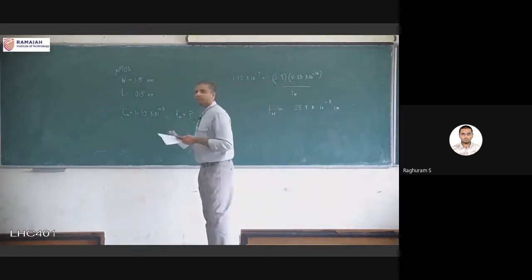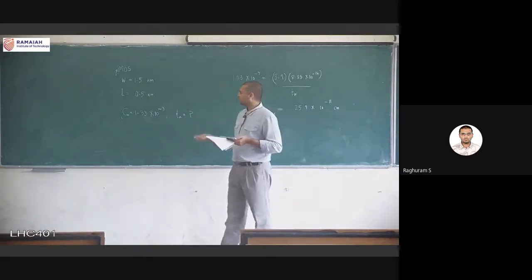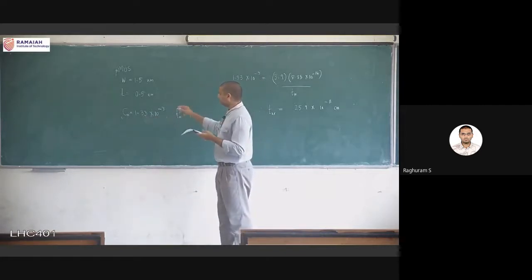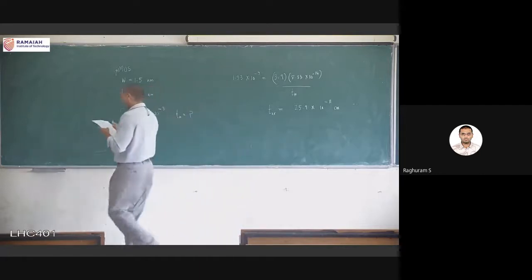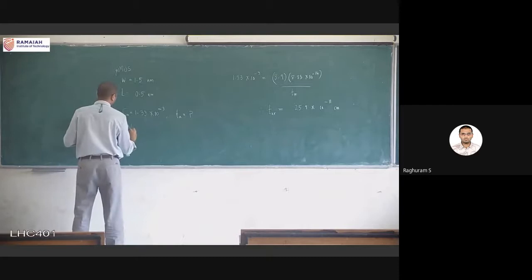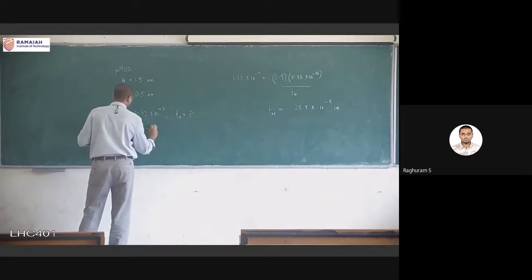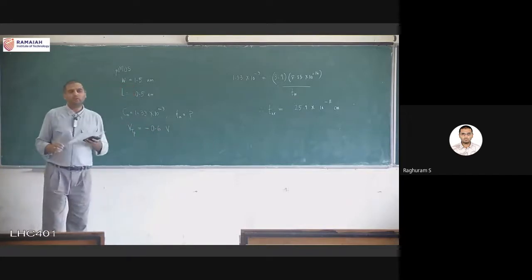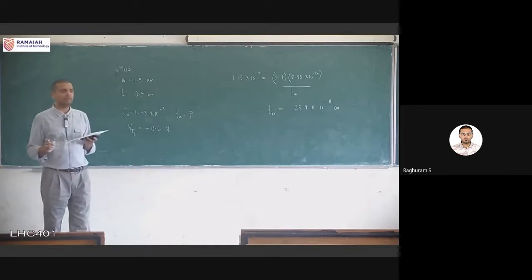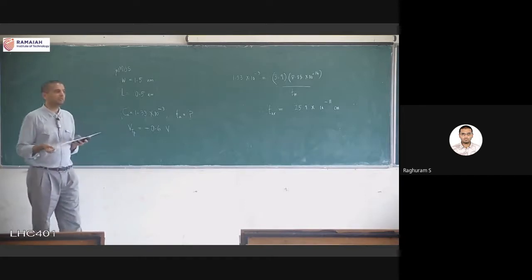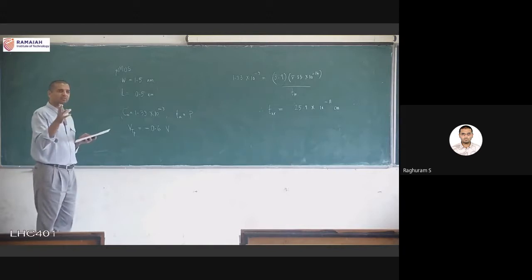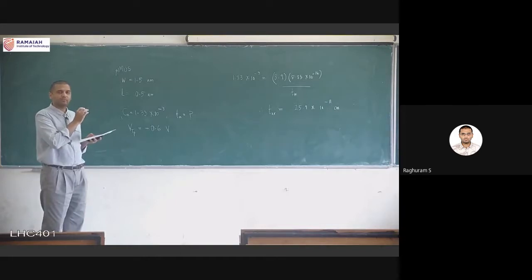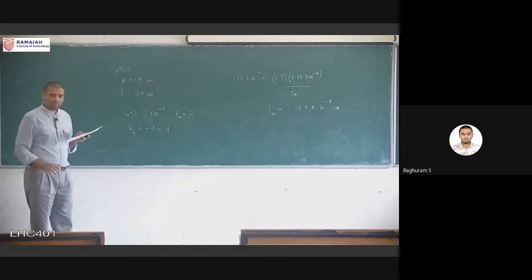And fortunately, we don't have to use this directly. They're just asking for it. We can use C oxide directly. That number is already there. So let us continue with this calculation. And VTP. Remember VTP for a PMOS transistor is a negative number. Negative number means that when you're using this in any of the calculations, you have to use the number along with the sign. Don't just take the plus 0.6 part. You have to put it as minus 0.6.